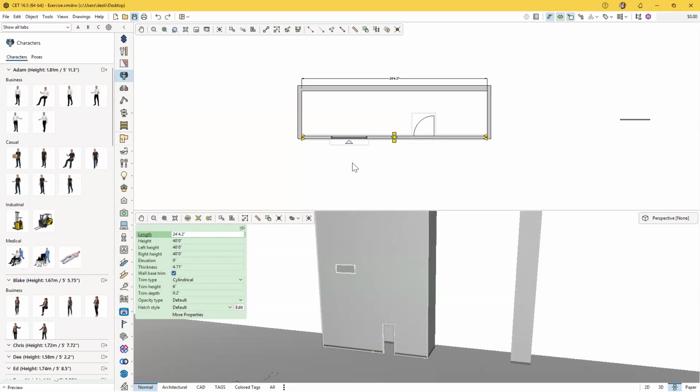This is especially helpful if you have things like columns in the middle of your drawing and you're trying to just select a bunch of stuff in the middle of your drawing, and it's going to pick up all of those columns as well. This prevents you from accidentally grabbing those architectural items.